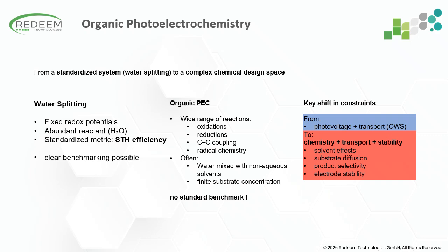As a consequence, there's no universal benchmark comparable to the STH efficiency, and reactor performance becomes strongly reaction dependent. So most importantly, the engineering focus shifts. Instead of optimizing only photovoltage generation and transport, reactor design must simultaneously address chemical compatibility, mass transport, product selectivity, and electrode stability in organic solvents.